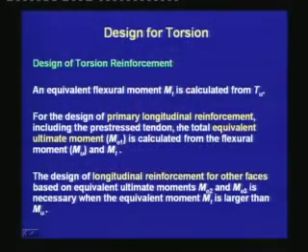The design of longitudinal reinforcement for other faces based on equivalent ultimate moments Me2 and Me3 is necessary when the equivalent moment Mt is larger than Mu.